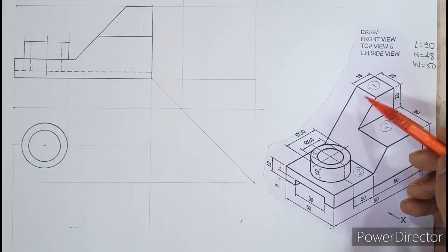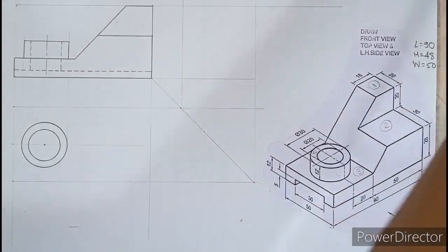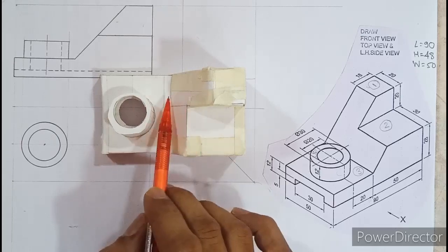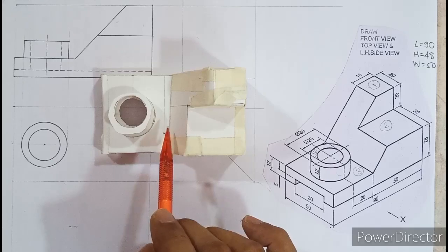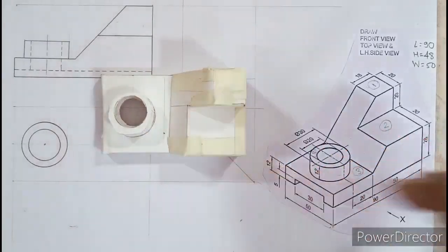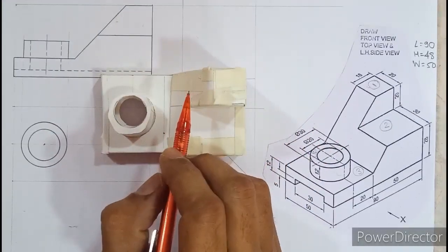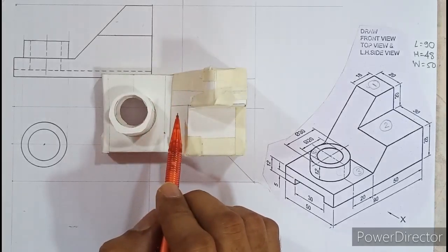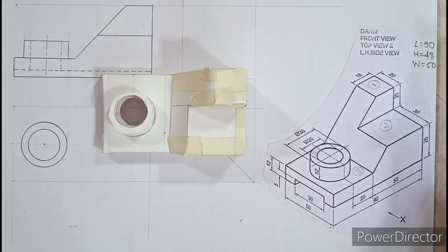Apart from this, if you observe thoroughly, you can also see some portion of the inclined surface. So if you look here in the top view exactly, you can see this inclined surface. But the question is, will this inclined surface be seen as exact shape or reduced shape? Yes, it will be seen as reduced one. And in engineering graphics, reduced means apparent. So you can see the apparent shape of this inclined surface. And actual shape means true shape. So there are two technical terms, true and apparent. True means exact, apparent means reduced.